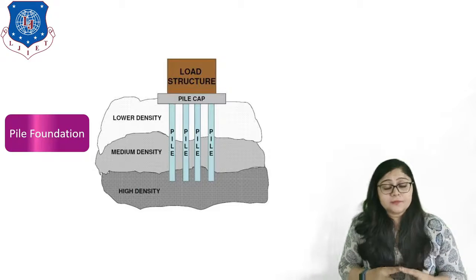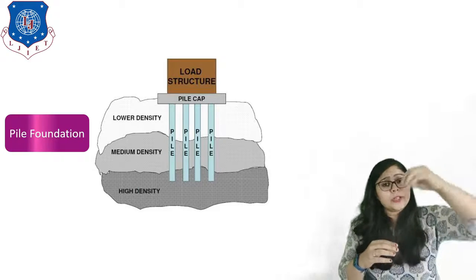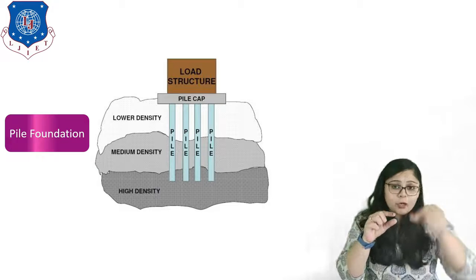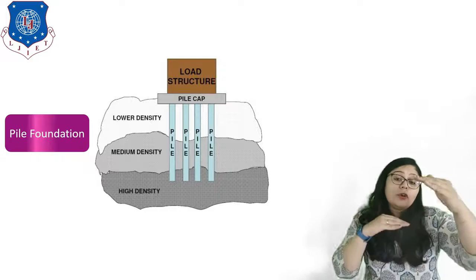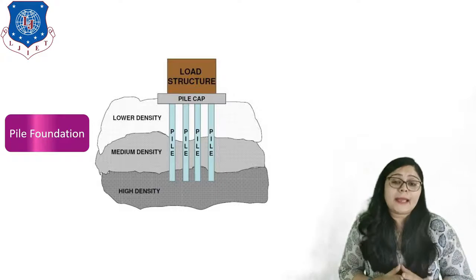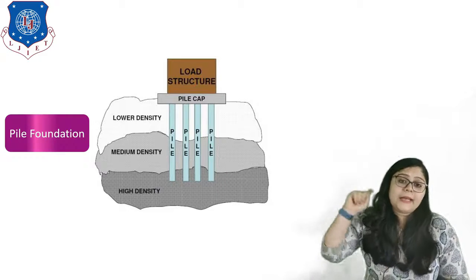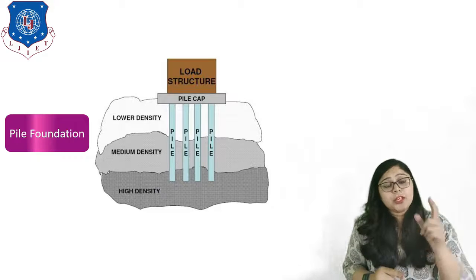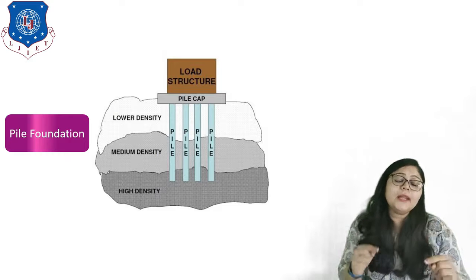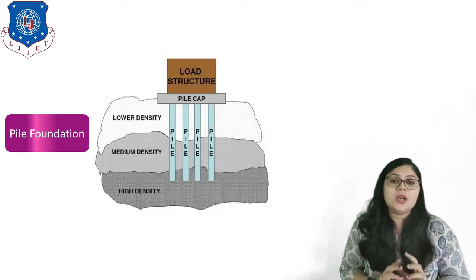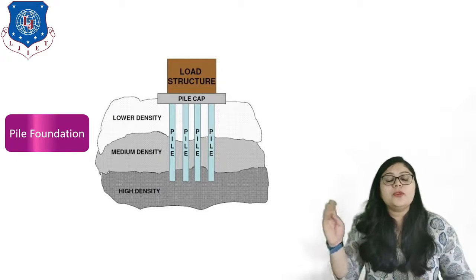But as I said, if I transfer load directly to that foundation or the piles, then it is not a practical solution. For that, I have to provide some cap that is known as the pile cap, which transfers the total load of the structure gradually to the piles and then to the soil. So this is the concept of pile foundation.